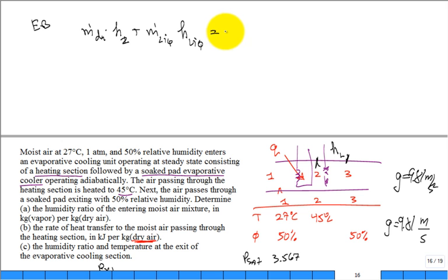Isn't that equal to the mass flow rate of the dry air going out times the mixture enthalpy going out? Is this equation good? I just did it from 2 to 3. The liquid comes in between 2 and 3, right, is added. I think this is a good energy balance, unless I have an error. Do you see an error, or is it good?